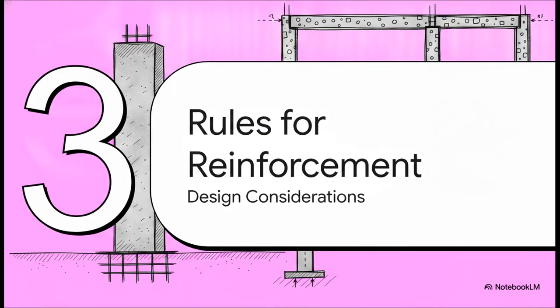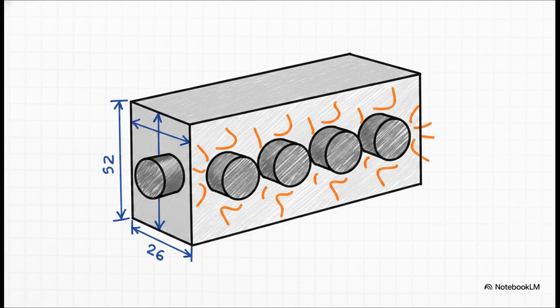All right, let's dive into Section 3, Rules for Reinforcement and General Design Considerations. So, we have our concrete mix dialed in perfectly. Now, this section comes in to strictly mandate the geometry and placement of the steel. It tells you exactly how steel reinforcement has to be spaced out, precisely how much concrete needs to cover that steel, which we call nominal cover, and how structural stress safely develops and transfers between the steel and the concrete. That transfer is what ensures the building doesn't just snap under tension. It is, quite honestly, a highly choreographed arrangement of metal and stone.